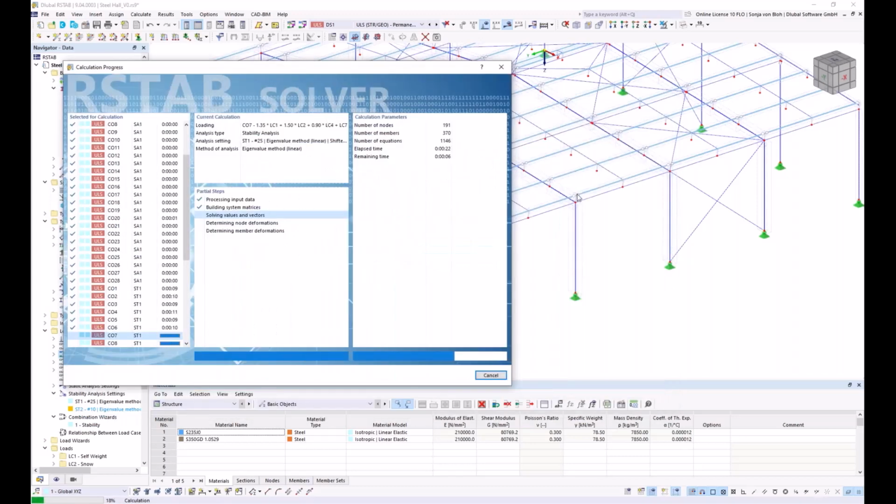The column is angled to the other frame, and this is the reason for this warning message. I assume that the warping can be transferred through the connection, so I ignore this warning message, and the warping is then transferred.